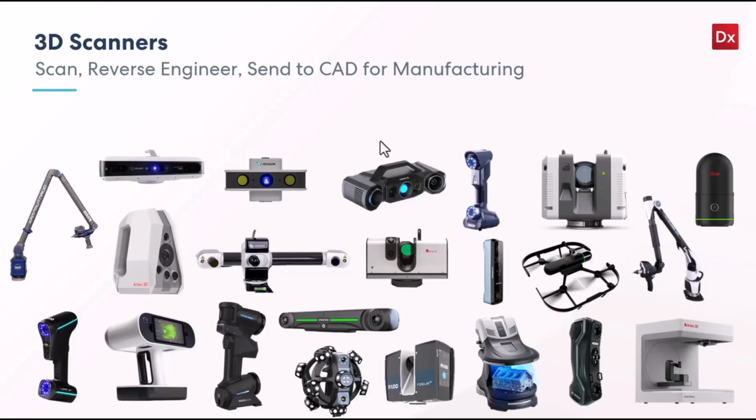Most of the time, you would probably end up using one that you could bring the scanner to the part in this instance, because these mold designs sometimes are very big and bulky. So you could use something along the lines of a portable CMM like this arm right here, or this arm right here, where you bring it out to the workpiece and scan it that way.